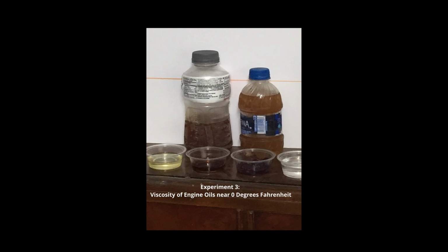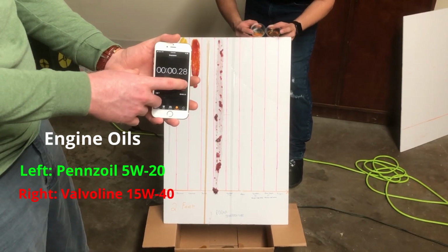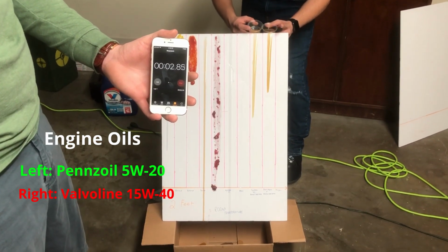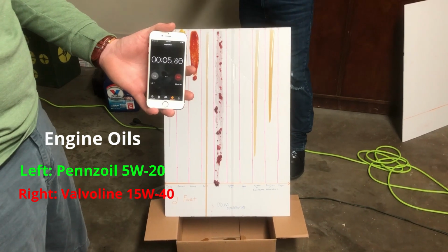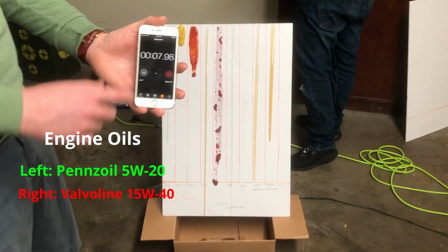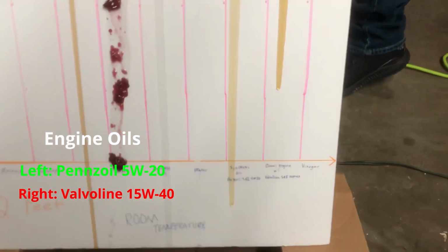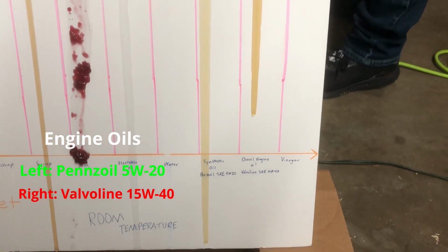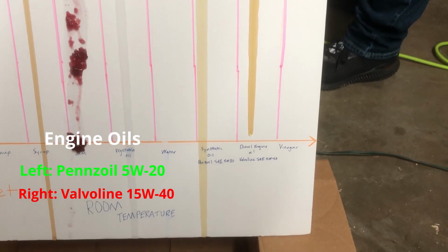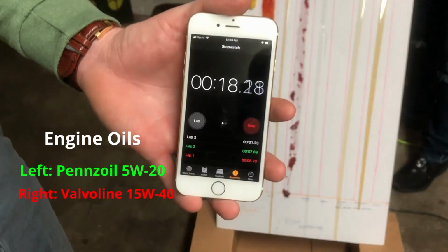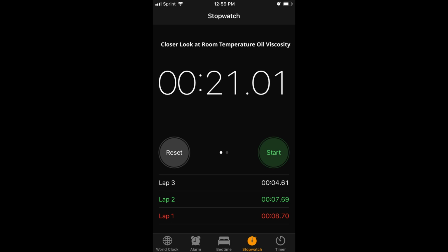The oils are synthetic oil, 5W20, used in mid to high performance car engines, and Valvoline diesel engine oil, 15W40, used in diesel engines. So synthetic oil is partially man-made and is engineered to reduce friction of the oil on the camshafts. It also does not have to be changed as frequently. Diesel engine oil is around the same price as synthetic oil and does not have the added benefits other than being a little thicker because of larger gaps in between mechanical parts. Diesel engines are a little bigger in size than the engines that synthetic oil is usually used for.